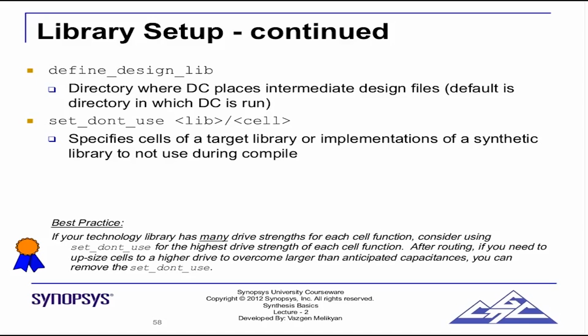I guess that's it. Yeah. So I'll just summarize what we saw today. We saw in detail how the standard cell library is made up, what type of cells it contains: the high drive, the multiple drive cells, different functions, different number of inputs, for example, 2 input NAND, 3 input NAND, and so on.